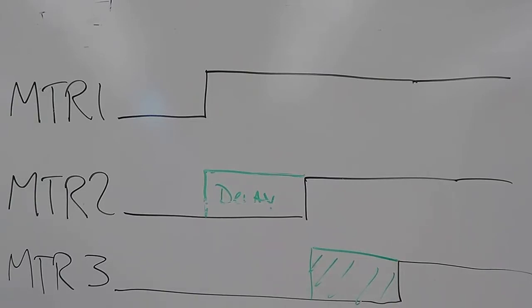And looking at the specification, if motor N is running and it's stopped before N plus 1 starts running, motor N stops immediately. And N, you can replace that with 1 through 6. So again, if motor 2 is running, but motor 3 has not started yet, and I hit the stop button, motor 2 stops immediately, and then the delay starts to shut down motor number 1.